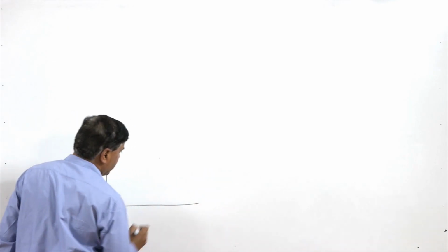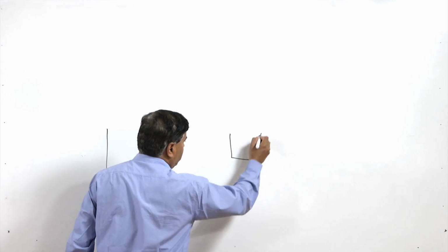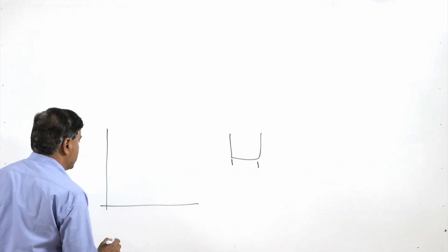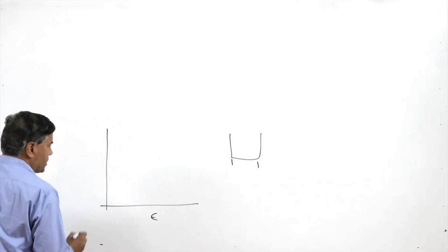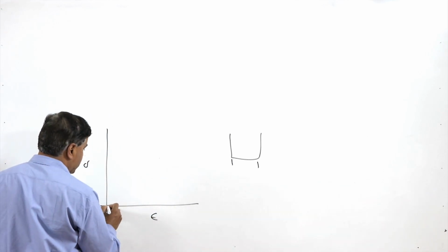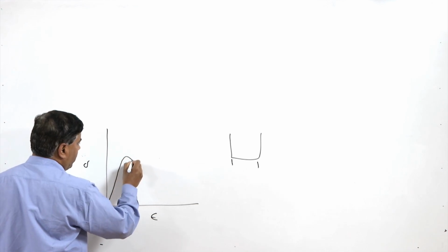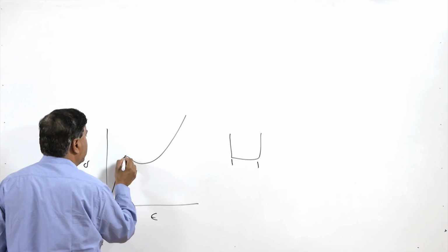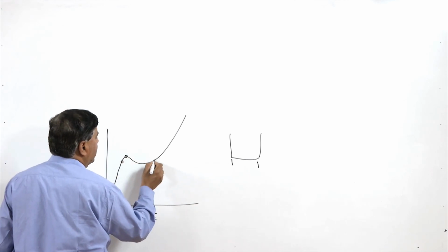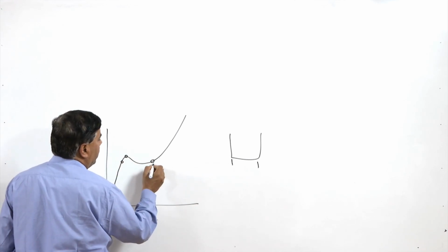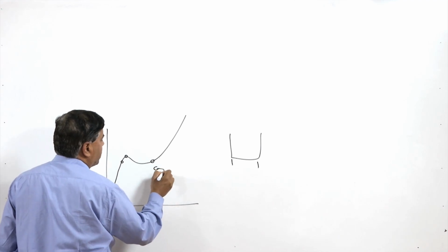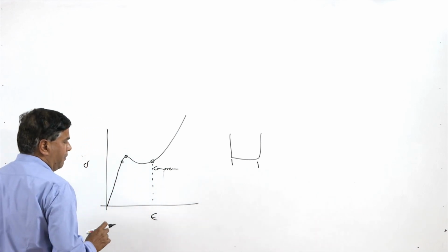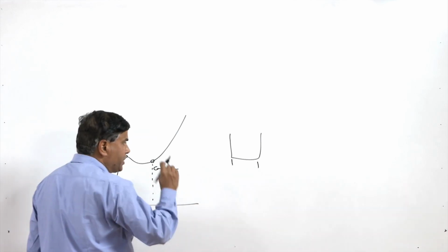Depending upon the distance traveled by the punch inside the sheet, we get different strains. As the punch moves down, it leads to increasing compressive strain in the sheet. So, the x axis is showing the strain and the stress is on the y axis, and the diagram that we get becomes like this. Here this is the yield point, this is the elastic region, and this is the plastic region where some compressive strain has been induced, of this much magnitude, due to the entry of the punch into the sheet metal.